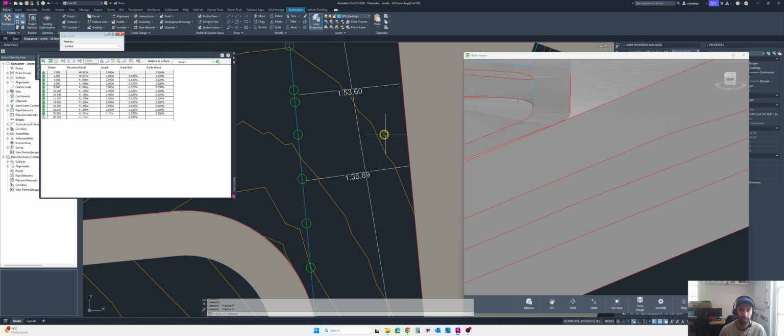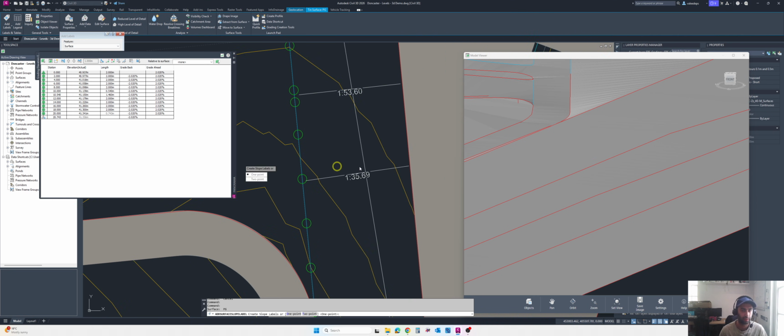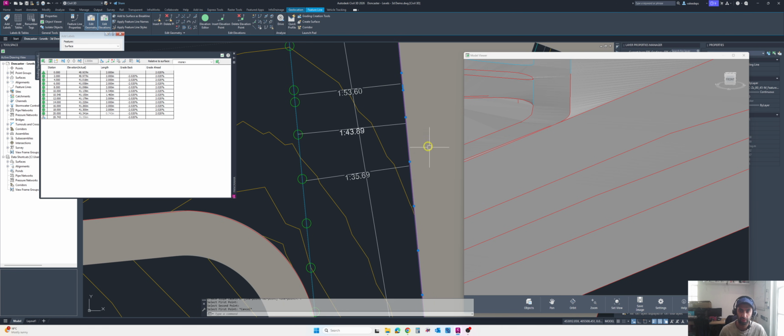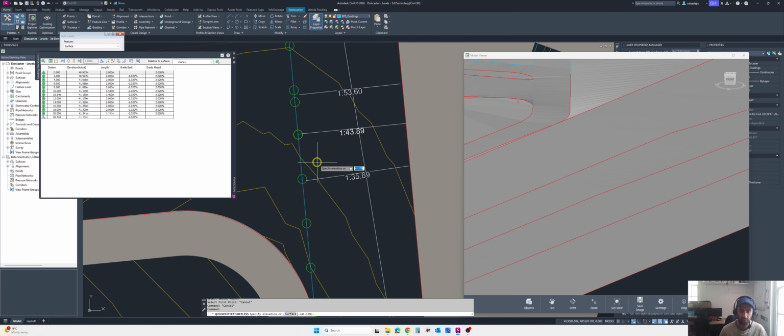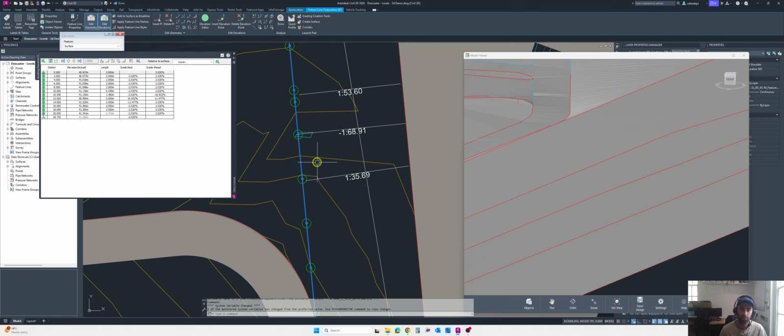So if I select my surface and go to the labeling, from this to this, 1 in 43, so this is higher than this level. So for example, I select this one, it is 41.061, and 41.061, and I would like it to be 40.990 maybe, so minus 160.